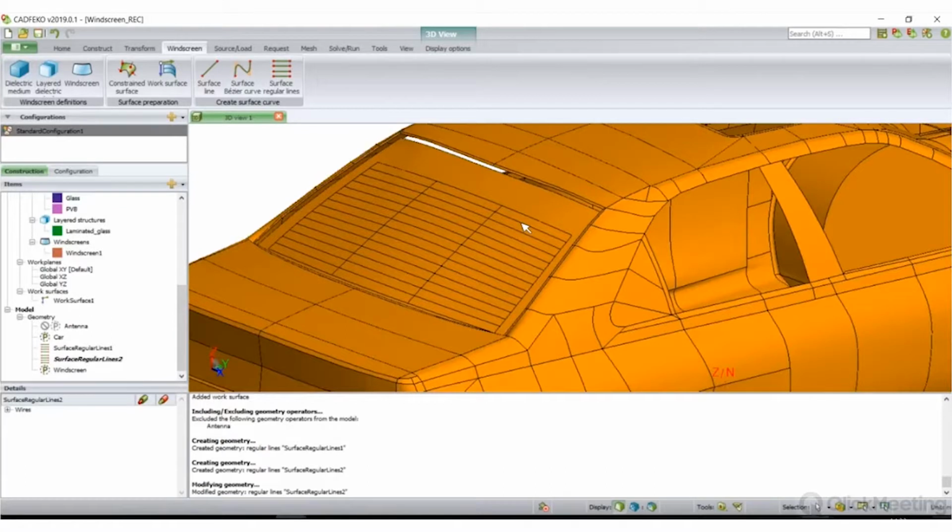These wires should definitely be included in the analysis because they are in the closest proximity to the antenna. And on top of that, the length of these wires is comparable to the wavelengths at some parts. So we definitely need to include this to have a proper result.